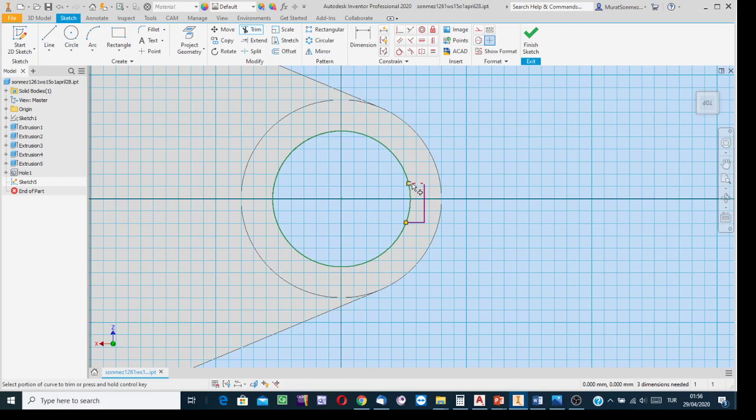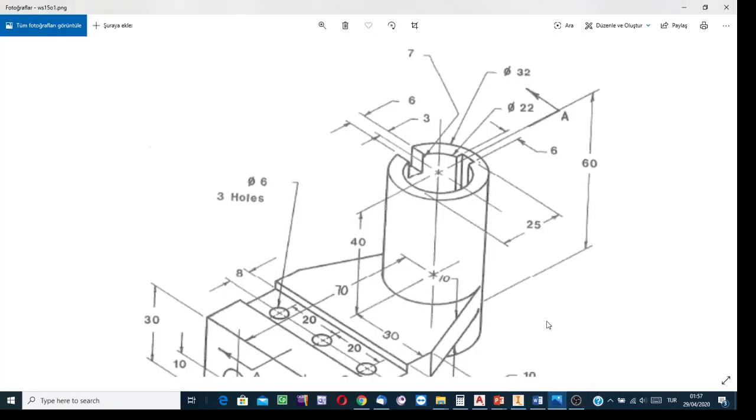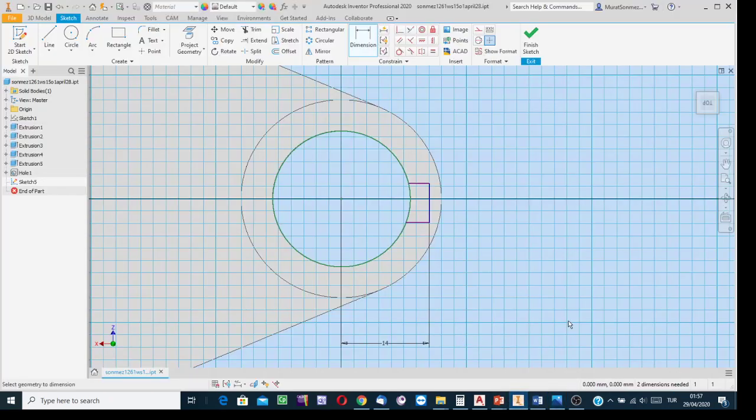And then yes, I had these lines, and in my mind these are the edges of the surface of the channel. And then I know location dimensions. Well, from the center to this line, I know that when I indicate the circle, its center point will be the reference. So, already calculated. Distance from here to there is 14. Am I true? 25 minus 11 makes 14. Yes. True. From here to there, distance 6.